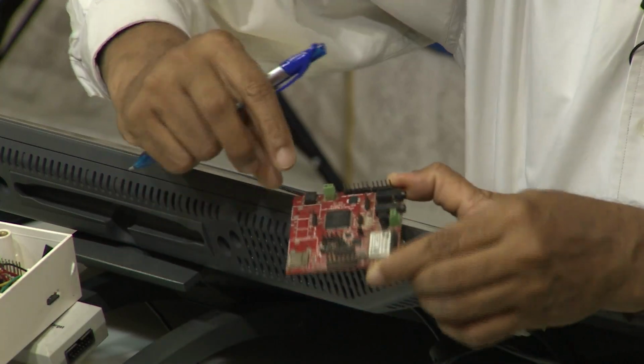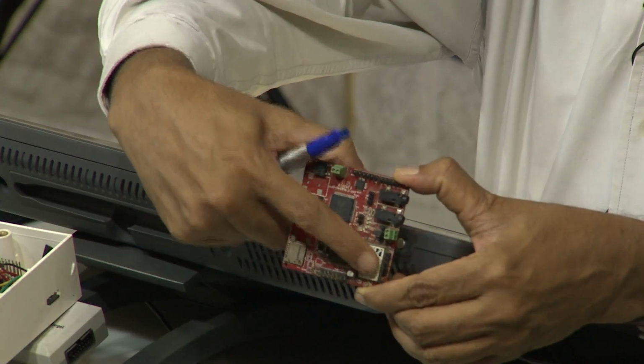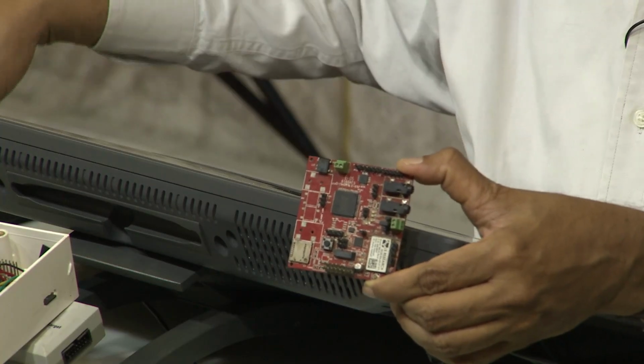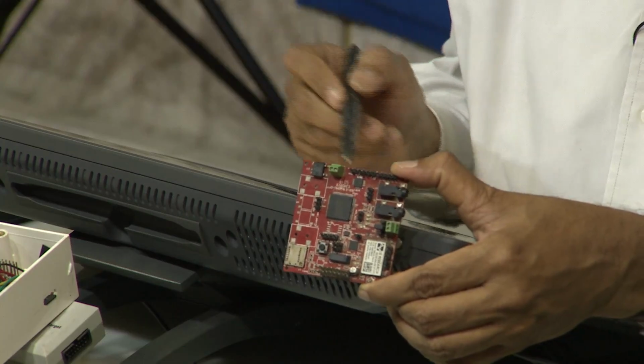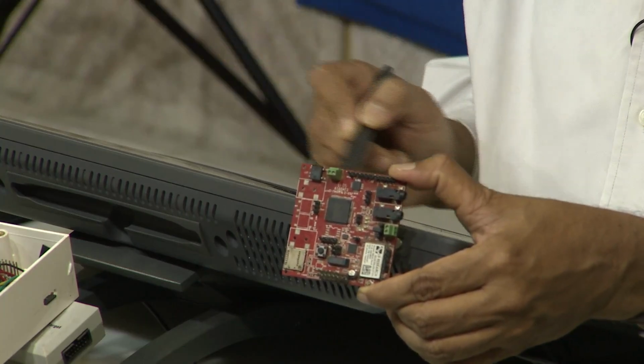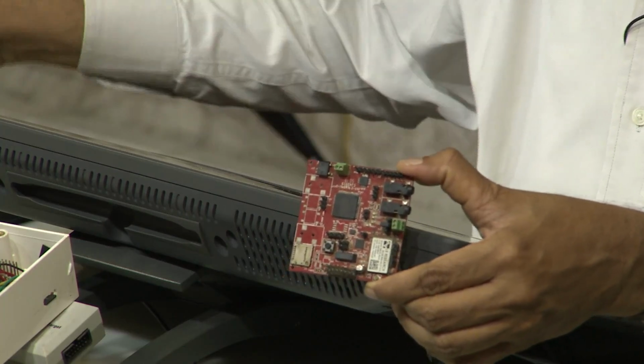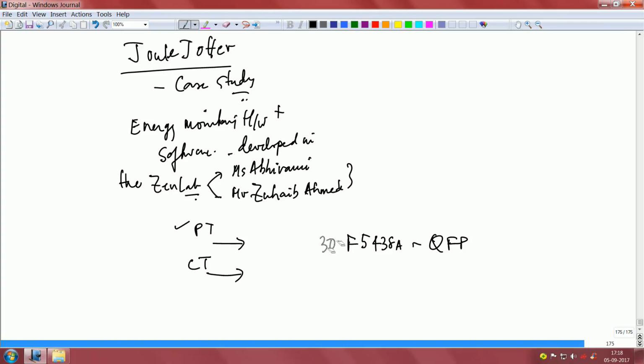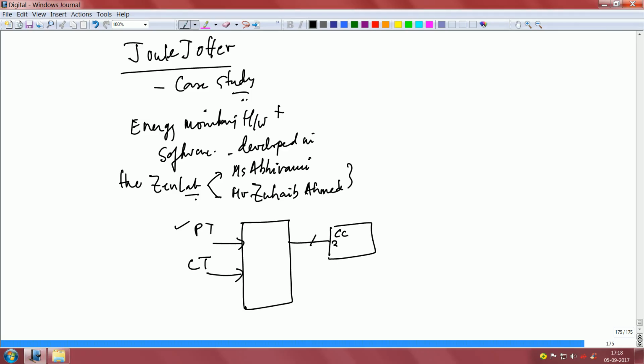This system that you see here, this is indeed the radio module, which is called CC 3000. For some reason this radio module gave us some trouble. We will discuss that interface to this radio module separately. So just to complete the schematic capture as we go along, I will write MSP 430 like this, and I will connect the CC 3000 through a SPI bus, right.